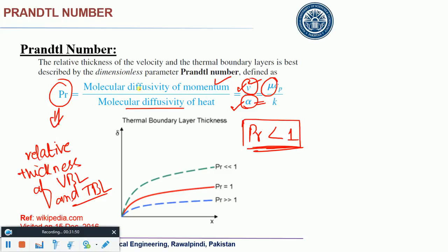Prandtl number greater than 1, obviously there would be a Prandtl number if you have heat transfer. The only thing is whether you need to diffuse the heat quickly, or you need to diffuse the velocity quickly, or friction or viscous effect quickly. You understand that these are the two things you need to decide about. You need to keep the velocity very low. But the question is to what extent? Right? If you use a liquid metal, or water, or oil, they have different mu's. Or even if you use a gas, they have different mu's.